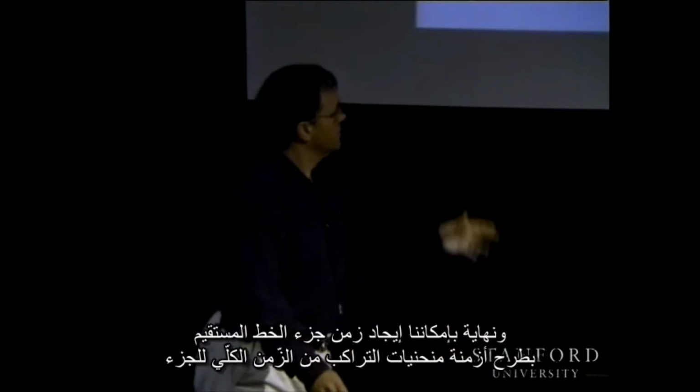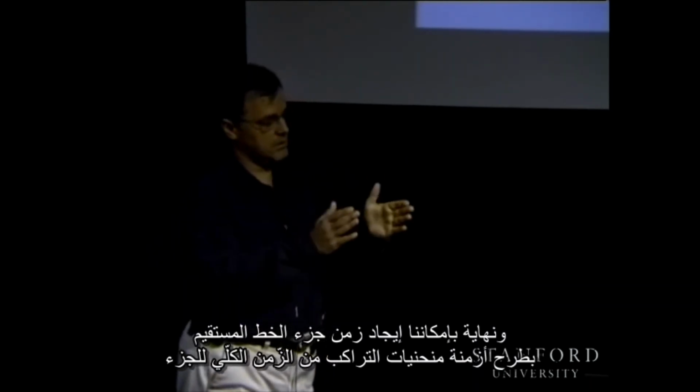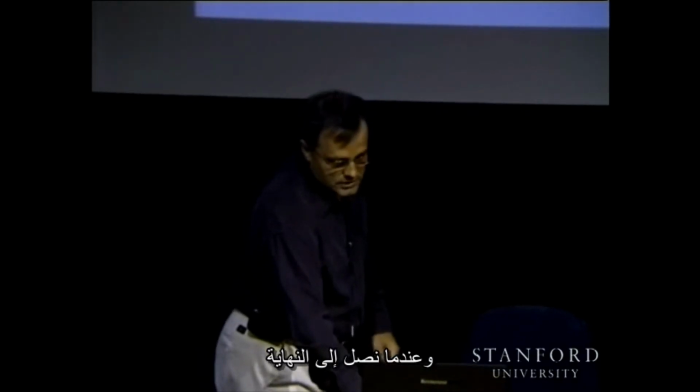And then finally, we can find the time for the straight line segment by just subtracting from the whole time for the segment the times for the blends. And as you see here, the blends here are half-half on each side. And then when we get to the end,